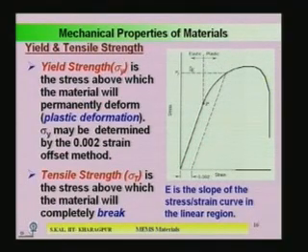There is a difference between elastic and plastic. Elastic means the stress-strain relation is linear, plastic means the stress-strain relation is nonlinear. There, deformation takes place and this leads to permanent deformation. In the part up to point P, if you release the stress, the material can go back to its original position, that is the elastic property.